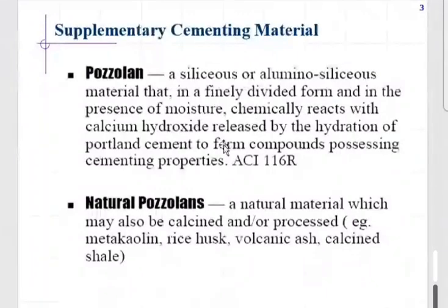Yes, sir. So this calcium hydroxide is already available within the cement. It can react with these siliceous materials and they make a secondary calcium silicate hydrate. That is even more stable, that reacts and that gets stabilized. This is the reason supplementary cementitious materials control durability chemistry-wise.